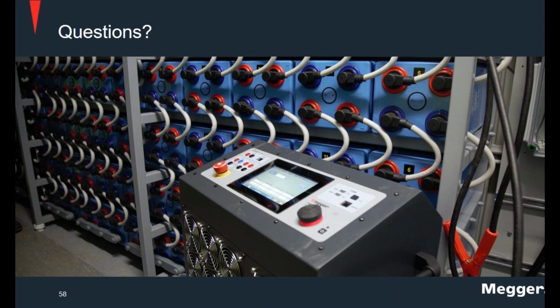So let's say for a battery with a service life of 20 years, you do a discharge test every 2 years, you end up doing 10 discharge cycles in that case. And you're not going too deep on the discharge either. So I would say that it does not reduce the lifespan. Taking a few cycles out of the life of the battery is not a big deal. And it's not a destructive test because you're not going too deep on the discharge.